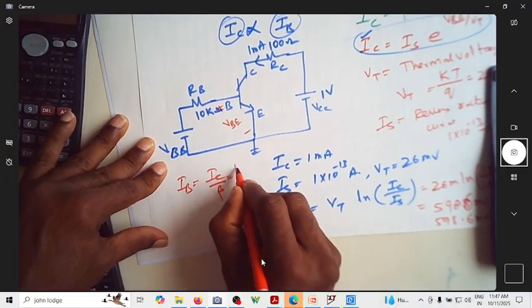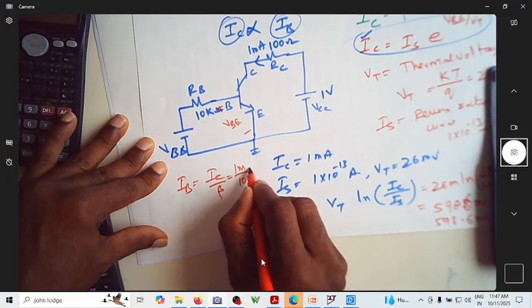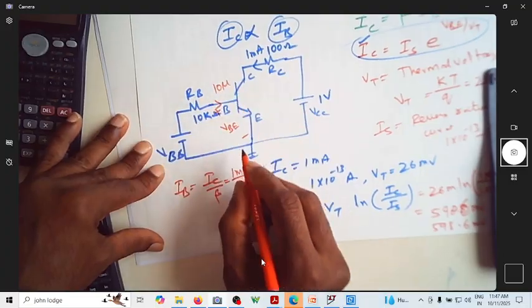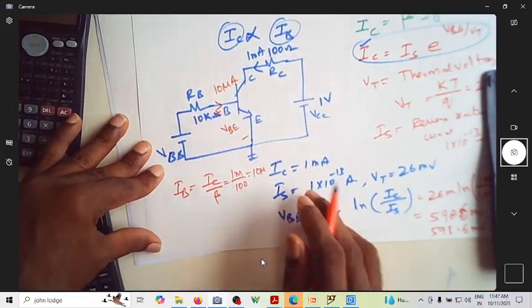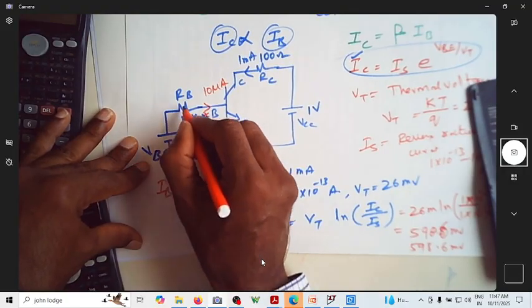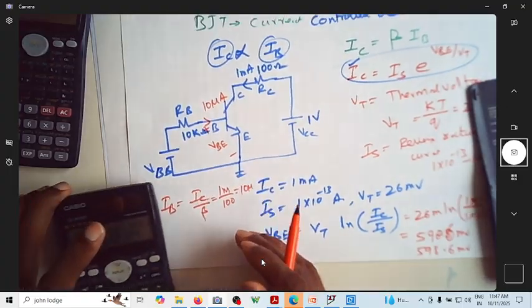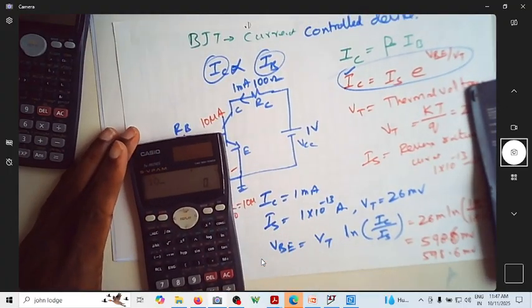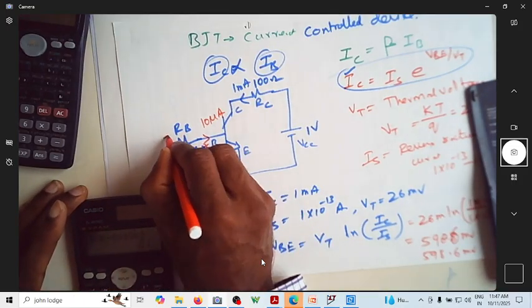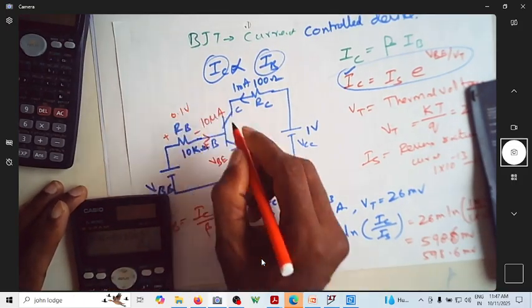So then this is 1 milli by 100, which is actually 10 micro. Suppose 10 microampere flows here with a VB of this much, then how much will be the drop? The drop is actually 10 exponential of minus 6 into 10 exponential of 3. Can you see you have a drop of 0.1 volt here.